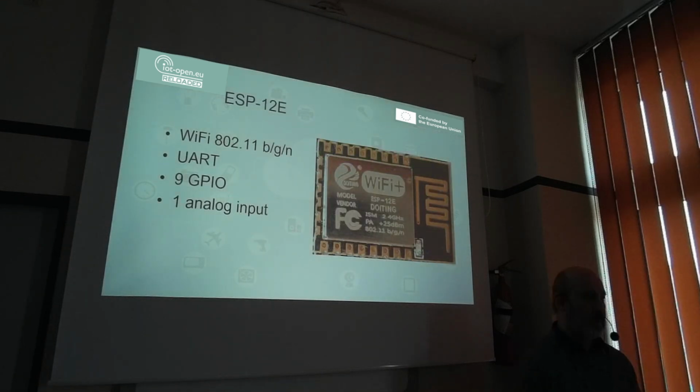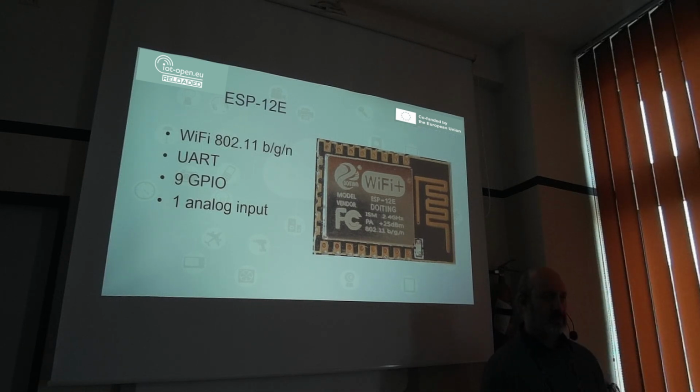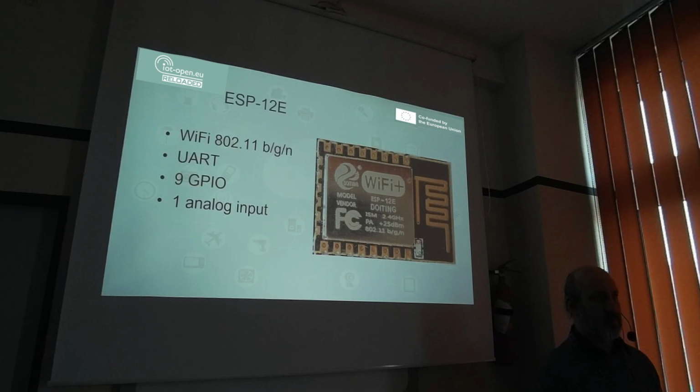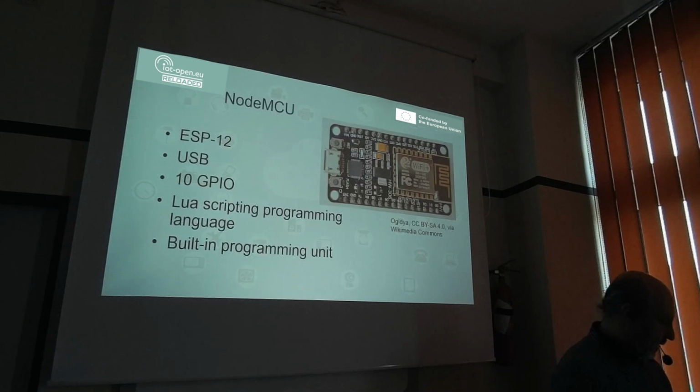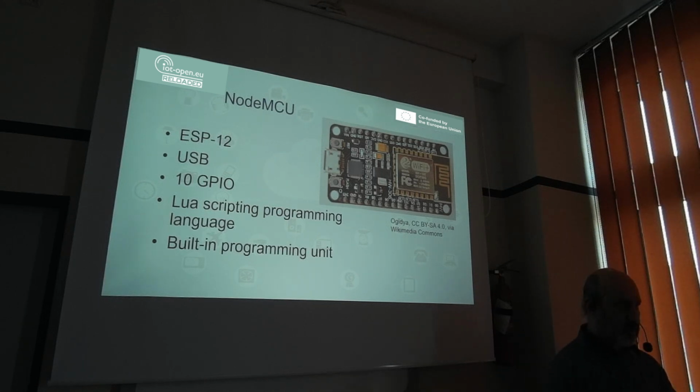Another module available based on this ESP8266 is ESP12E. As you can see, it has more pins around, but it needs some special board to be soldered. A very popular module named NodeMCU is based on this ESP12 module soldered in already, so it's quite easy to use.